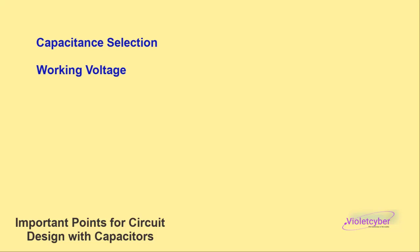The next one, capacitor type. The type of capacitor is chosen based on the circuit's application. For high-frequency or RF circuits, ceramic or mica capacitors are more suitable. For energy storage or filtering, electrolytic or tantalum capacitors are used. Polarity. Some capacitors, like electrolytic and tantalum, are polarized and must be placed correctly in the circuit. Reversing these capacitors may cause damage.